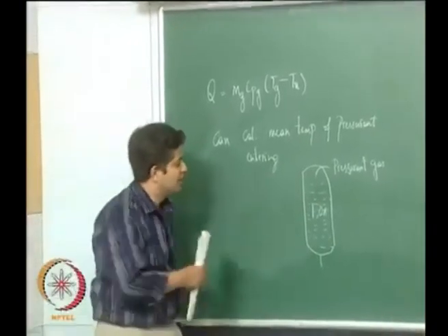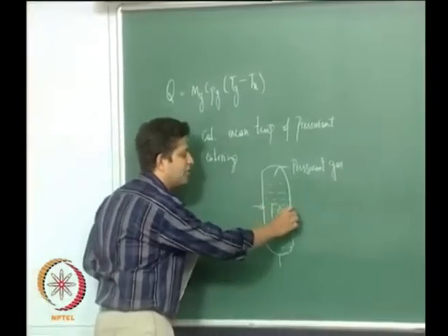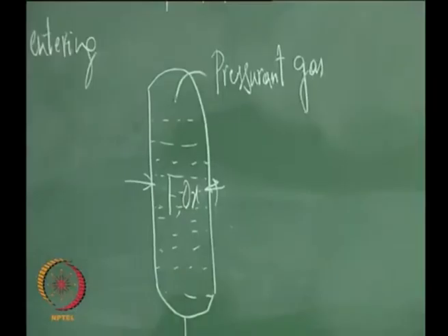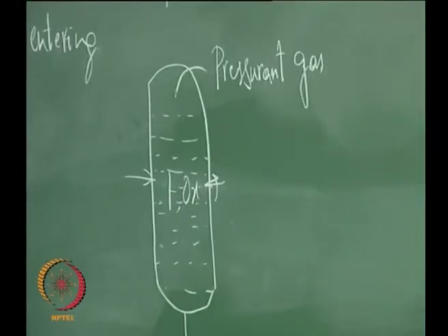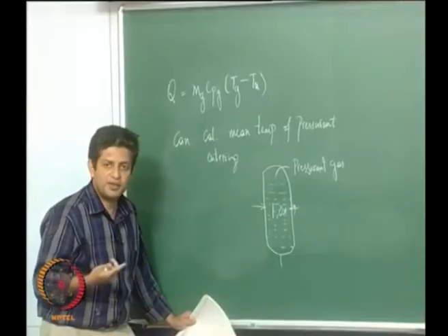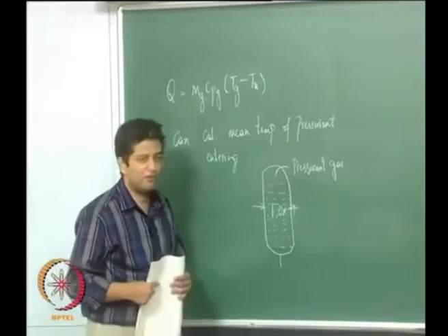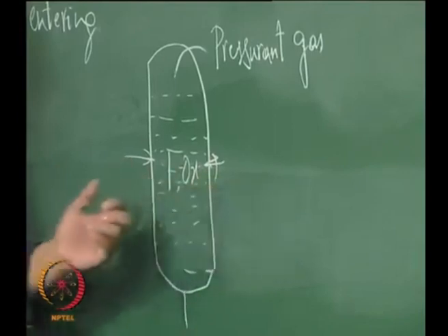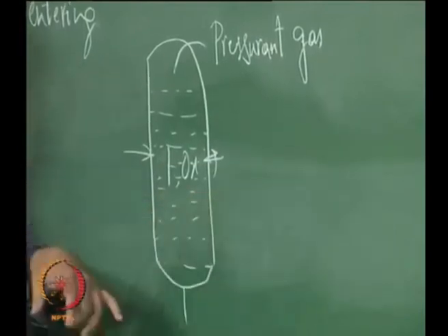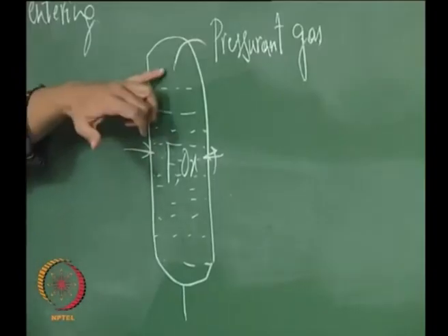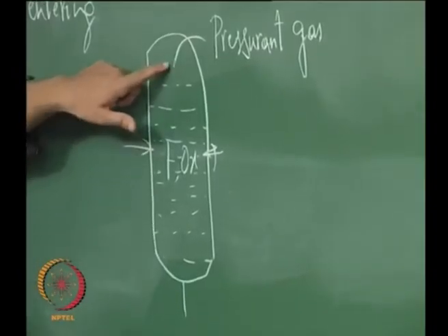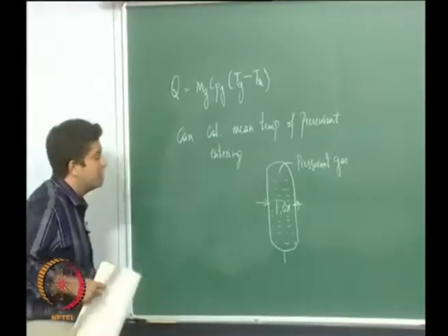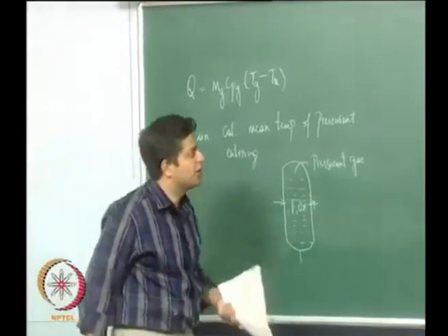There is also a possibility that heat might be transferred from the walls to the propellant, and therefore, there will be extra vaporization that will happen, right. Depending on the temperature of the surroundings, it might also happen the other way in some cases, wherein if the temperature of the liquid is higher than the ambient temperature, you could have reverse transfer. So, we have to account for that also, and also the case wherein the pressurant is transferring heat to the wall, right.